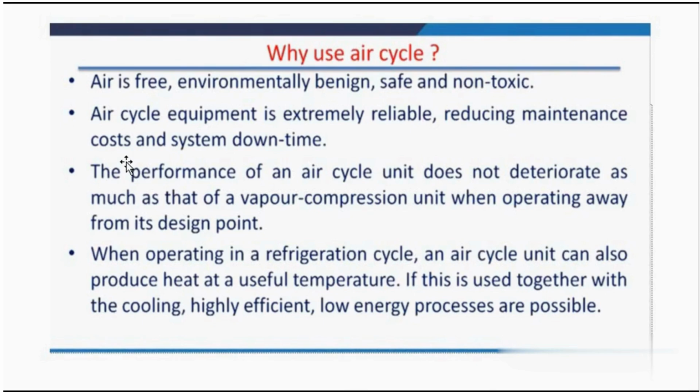Then air cycle refrigeration equipment is extremely reliable. Their maintenance cost is very less, and the system downtime of this cycle is very less. As well as, the performance of an air cycle unit does not deteriorate, as compared to that of a vapor compression refrigeration unit, when they operate away from the design point. The design point is nothing but a standard operating point which will give us the optimum performance in real life.